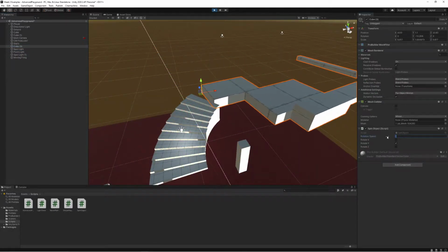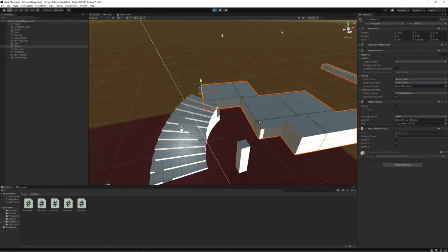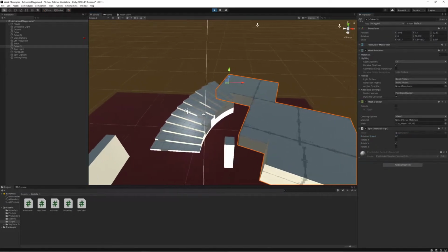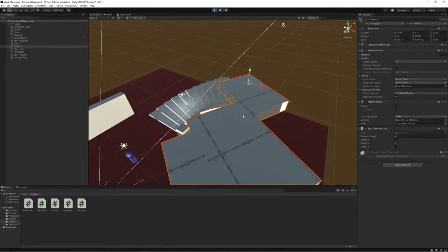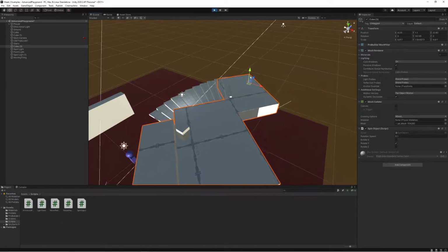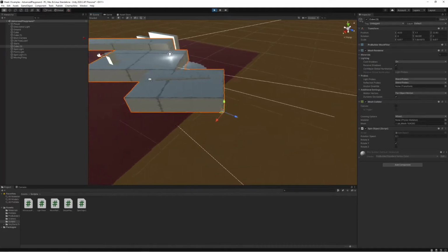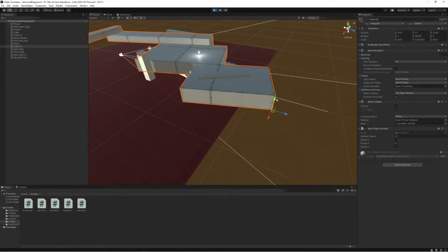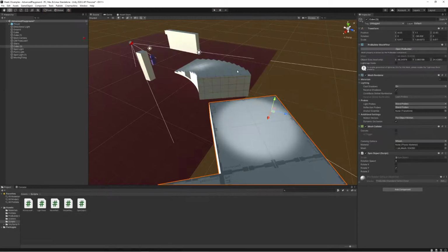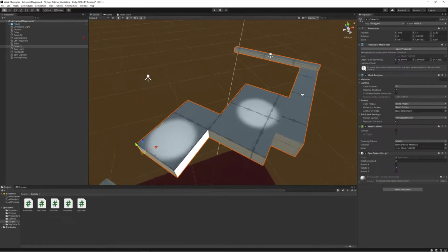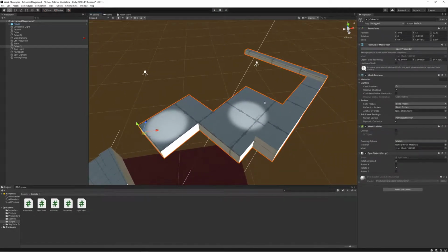Where I can maybe crank this down a little bit, but think about having this part of the level itself rotate. Now, something I notice here is why is it rotating around this edge? Well, that's the starting reference point, and everything references around that particular coordinate where the shape is built from. Is there any way that I could change this so it rotated instead around a center point over here? Let me show you a little strategy.